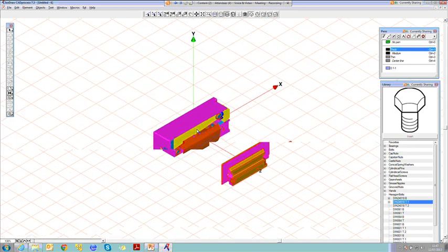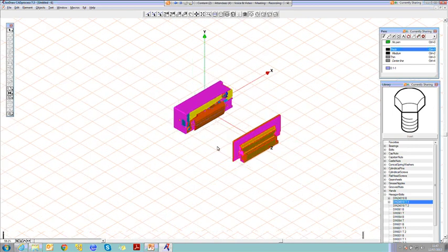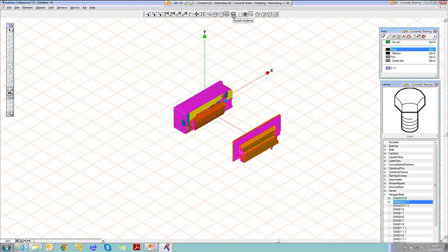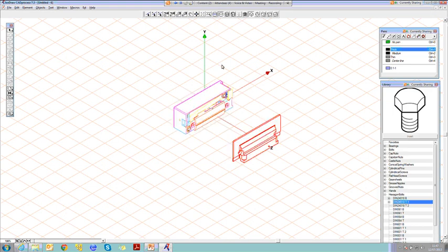You might then zoom in a little bit, and if I change the orientation or the viewing options, you've got some viewing options up here, whether you view it with hidden line removal, in wireframe, in rendering or smooth rendering, which puts a little reflection on it. This is just for the purposes of while you're working on the CAD illustration.